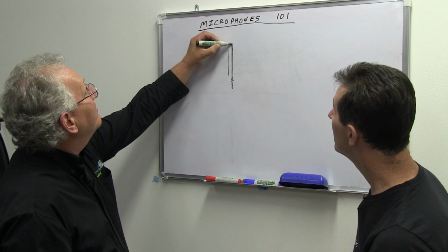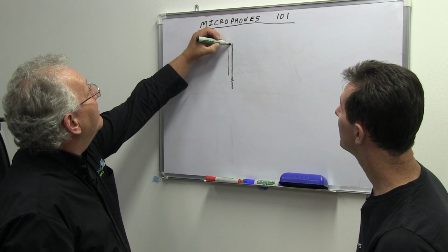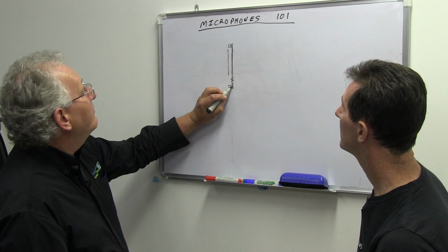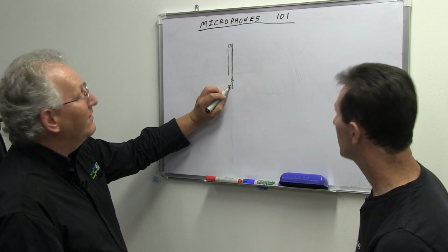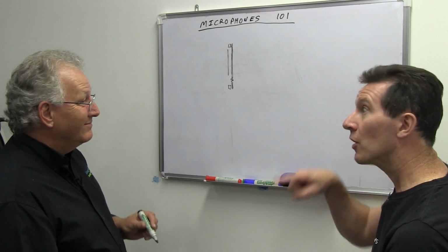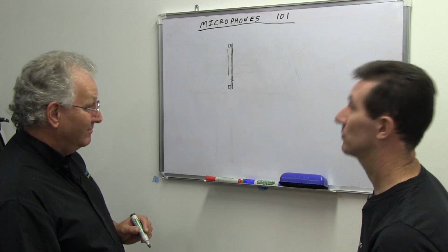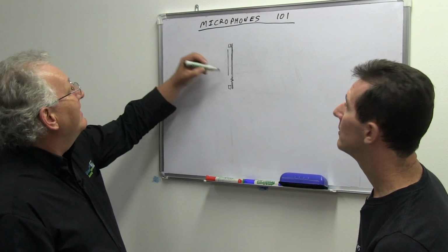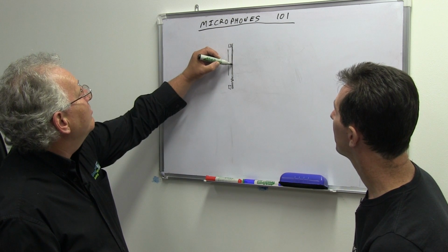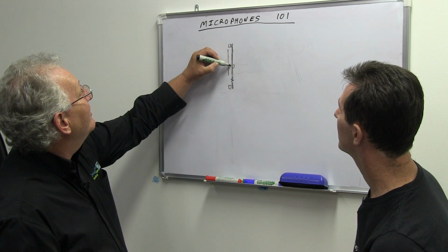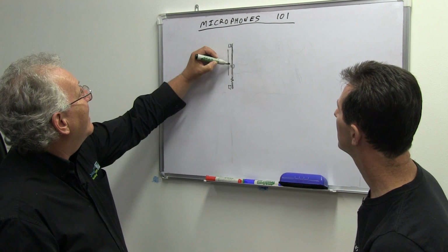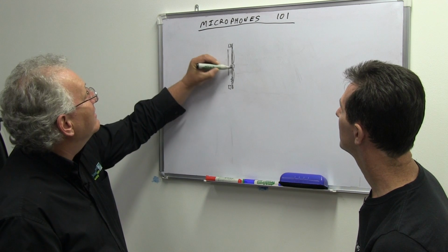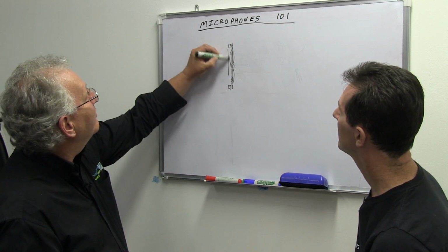In fact, let's take that right to the edge. It's glued onto a ring, and it's either a conductive glue between there and that ring, so it'd be the entire circular ring that conducts through, not just one point. And just occasionally, and I've got an example here, you'll see they actually put a screw through the middle there, and so that forms an annular shaped diaphragm, because it's that bit that vibrates.